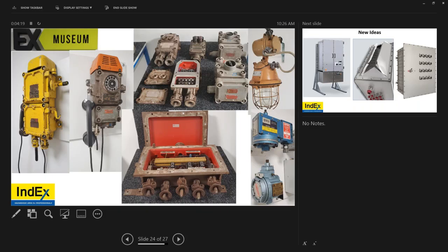Can we supply without internal wiring to the end user? For flameproof? Yes. If it's just a device that you have, you could have a device mounted in there just with terminals where they have to bring their incomer and outgoer cables. Yeah, you don't need the internal wiring.